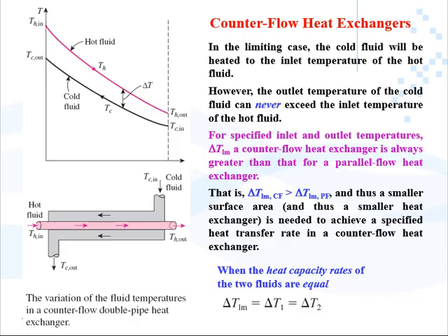But in the counterflow heat exchanger, that's not the case. The cold fluid temperature at the outlet can be much higher than that of the hot fluid outlet temperature. So that's something that you need to keep in mind.